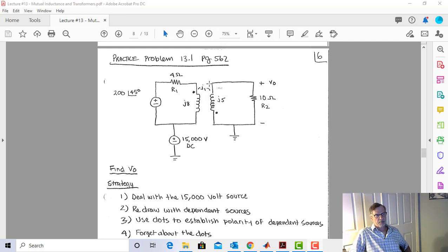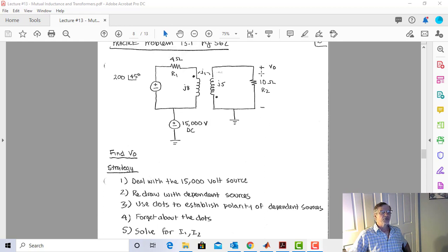Engineers use that to make devices safer, because the transformer will give them isolation from DC. It was one of the sales pitches for transformers, and now you can see it. If you don't like the idea of there being 15,000 volts DC anywhere in here, go back and look at it more. There's no return path for DC. That DC voltage is not going to make currents go around this way. Convince yourself of that.